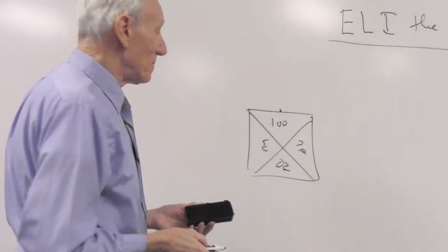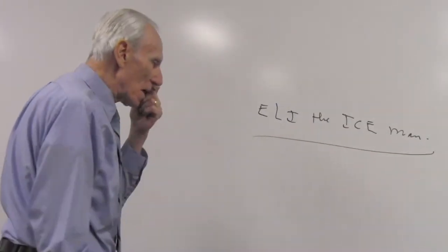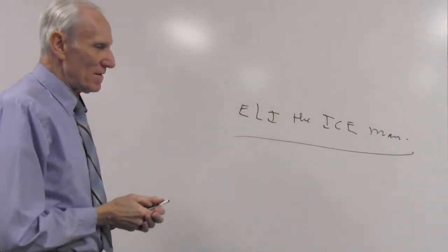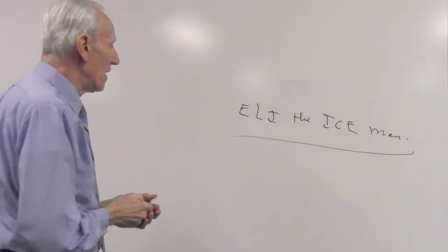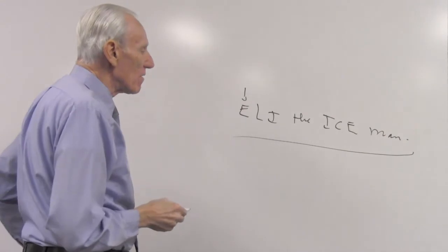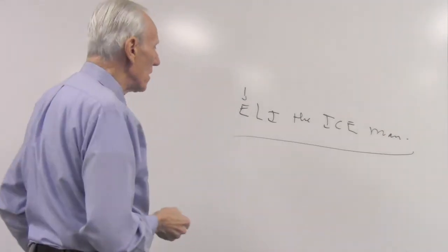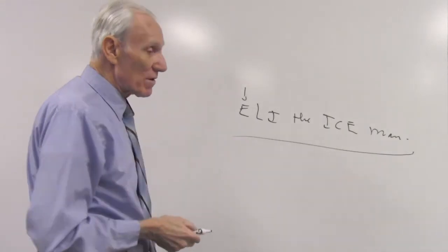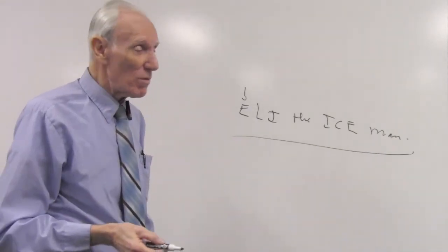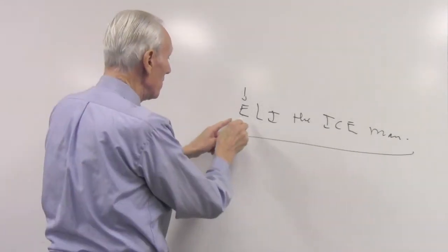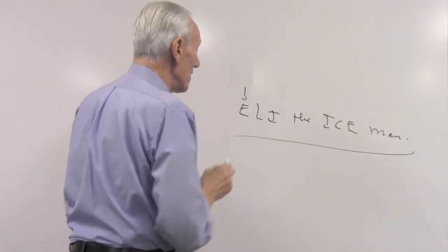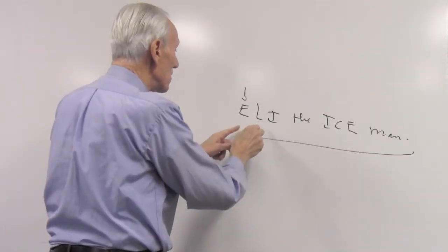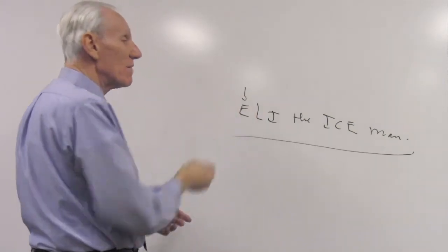I got my treat. So this tells me which way is what in terms of my phase diagram. I don't know if you've talked about EMFs yet, but EMFs are just voltages, or a form of a voltage. They're called electromotive force, but they're not a force, they're a voltage. So if the voltage comes before the current, if the voltage is in front of the current, then I have ELI.